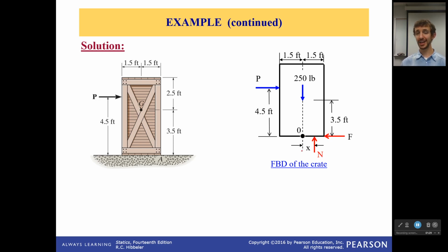And so we really just need to figure out what X, N, and F are, and P. That's 4 unknowns. We only have 3 equilibrium equations. And you're like, well, wait, we know what the normal force is because it's just equal to the weight. That's one of your equilibrium equations, the sum of the forces in the y direction. So don't confuse yourself by thinking you can't get away with it. You'll quickly find that you can. Just don't start off by getting confused.